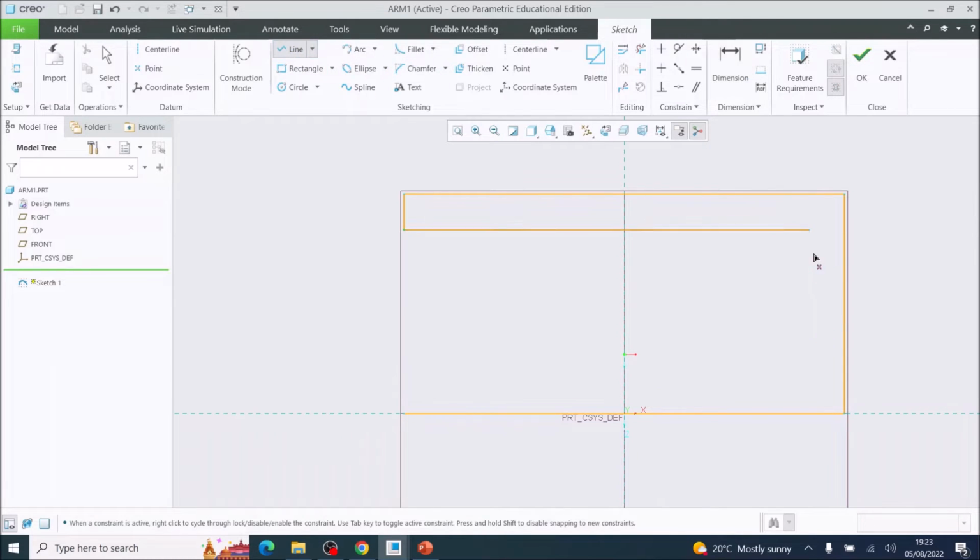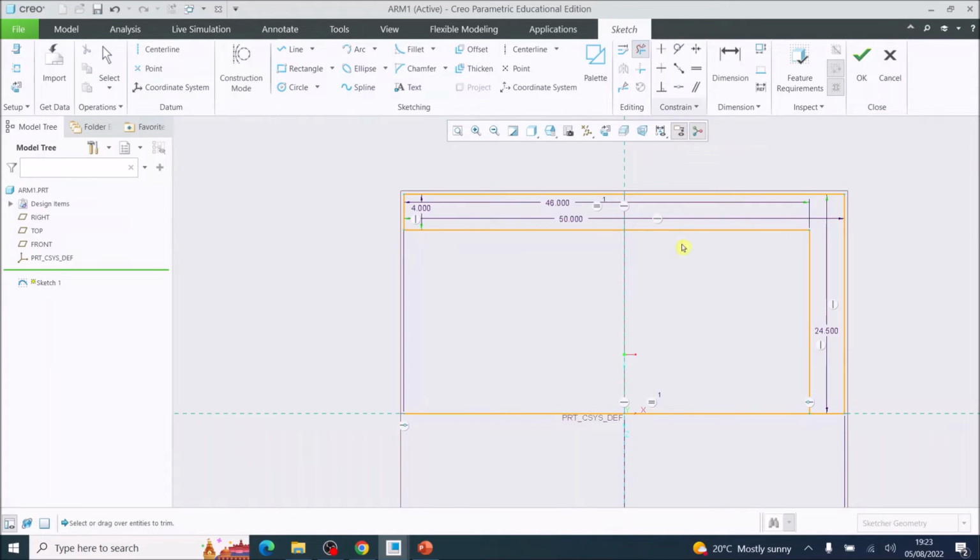And then I'm going to click on there and bring it to this central line, and then disconnect. Okay, so now I'm going to use the delete segment tool, and I'm going to delete the original central line plus the line that is here.